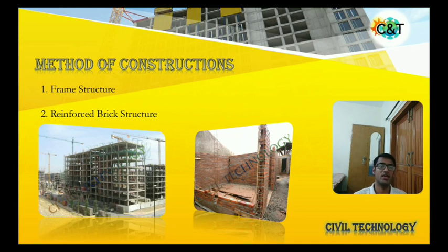Then in that case, the frame structure gives you that flexibility. You can construct additional stories later also, after a few years. But in a reinforced brick structure, you can't construct an additional story once the construction is over. So this is a disadvantage of the reinforced brick structure method, but obviously a certain cost will be involved along with those facilities